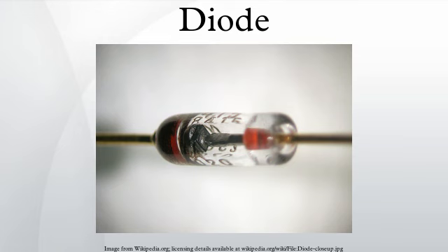Constant current diodes. These are actually JFETs with the gate shorted to the source, and function like a 2-terminal current-limiting analog to the voltage-limiting Zener diode. They allow a current through them to rise to a certain value, and then level off at a specific value. Also called CLDs, constant current diodes, diode-connected transistors, or current-regulating diodes.